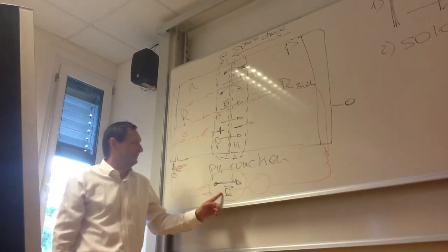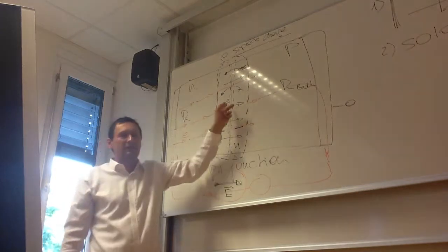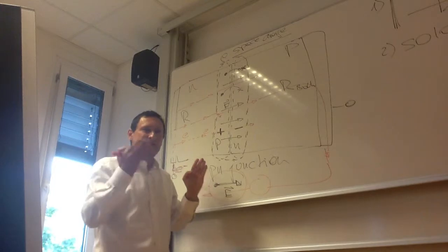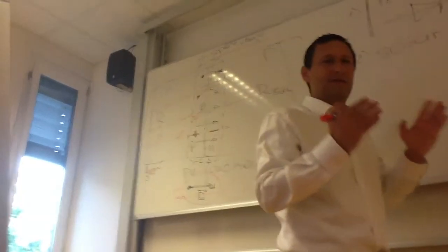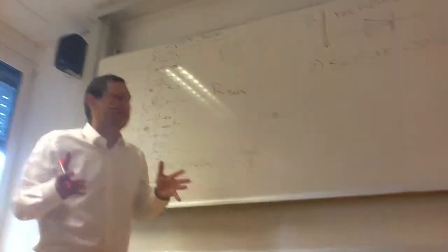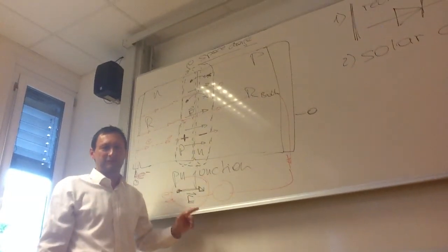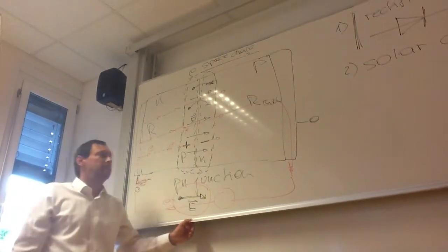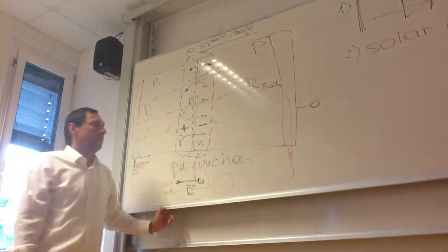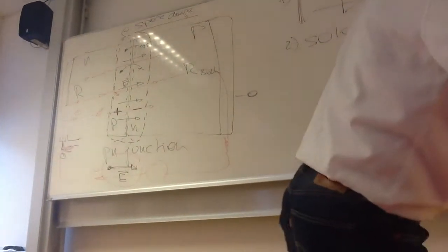And the electric field emanates from the diffusion of the electrons from the N to the P area, and the amount of electric field is characteristic for the semiconducting material, for example silicon or gallium arsenide, whatever you use. That means that you have some losses across your junction. So it's not an ideal rectification. But if the electrons move the other way around,